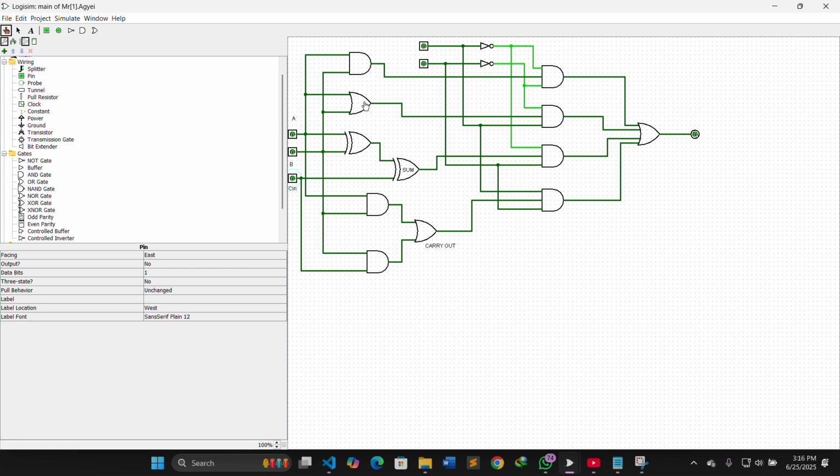If we want to display whatever is at this OR gate, we simply switch the top selector input to 1, and it will display whatever is at this OR gate. If you want to display what's at this SUM gate, which is what you want to do right now, we simply switch here back to 0, and then we switch here to 1. Now, when we switch this part to 1, what do we see? We see that our sum is indeed 0.